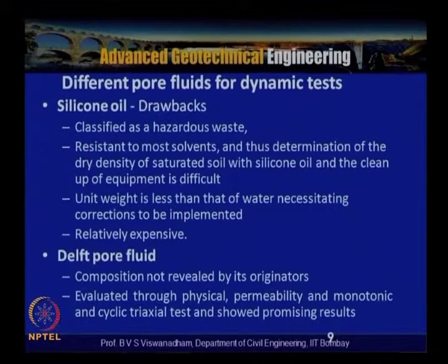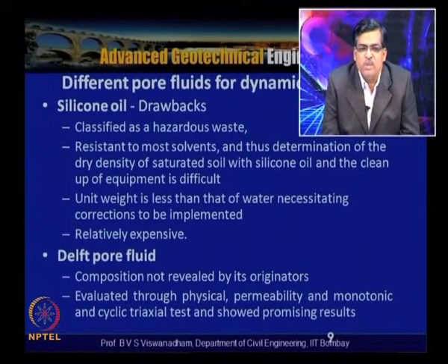The first one to be used is silicone oil, classified as hazardous waste and resistant to most solvents, and thus determination of the dry density of saturated soil with silicone oil and the cleaning up of the equipment is difficult, and its unit weight is less than that of water, necessitating corrections to be implemented, and it is relatively expensive.